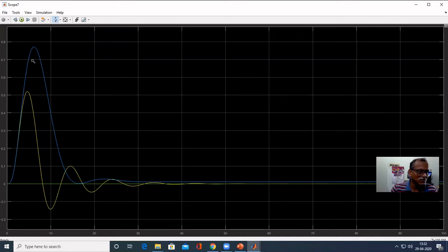It has large overshoot. Notice that we designed the controller for servo problem. What we designed, we are assuming that y of z by y set point of z is a first order plus dead time response. We didn't do any assumption for load changes. That's why it is not designed for load changes. Obviously, it has poor performance for load changes. But for servo response, it gives better response than deadbeat controller.